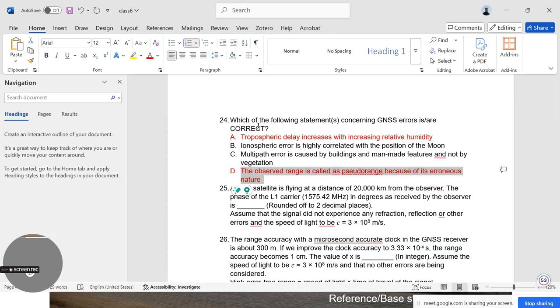So that's why when we fix a location of any permanent GPS point, we will find a location which is quite up in the sky, basically a very plain area where nothing is there, or else we can fix it on a terrace where we do not get most of the time obstruction from nearby buildings, trees, or any other objects.